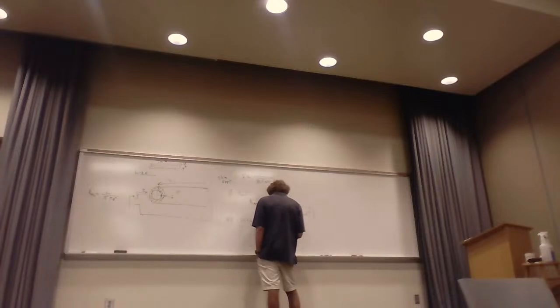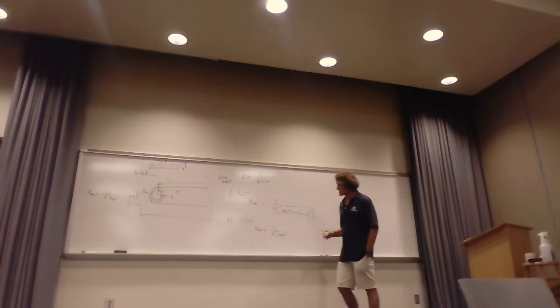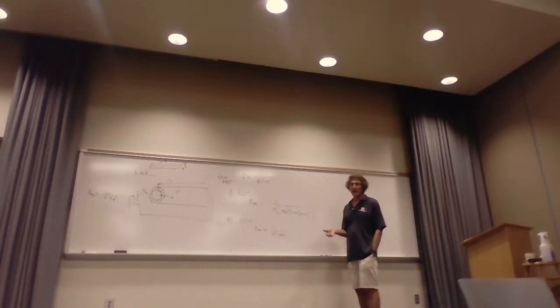That's going to be the AC resistance when you get into high frequencies, or when the skin depth is significantly less than the actual radius. And by the way, this is the way it is most of the time when you have anything that's over maybe a couple hundred kilohertz. The wires could be hollow, it wouldn't change things.